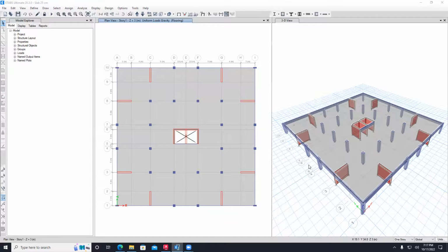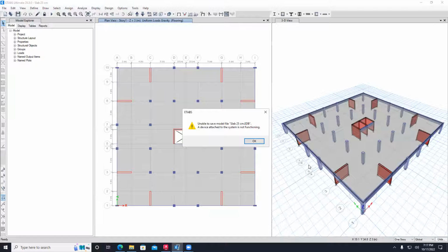They are invariable. So they put an equivalent stiffness K and do multi-degree of freedom analysis. When an earthquake happens at the base, all these masses will move. So that's what I care about. I don't care what the mesh looks like inside, because I don't care about the bending moment at this stage. I only care about the normal force, the bending moment and the shear force on the columns and the shear walls. That's why we build a 3D model to design the columns and shear walls, and a 2D model to design the beams and slabs.